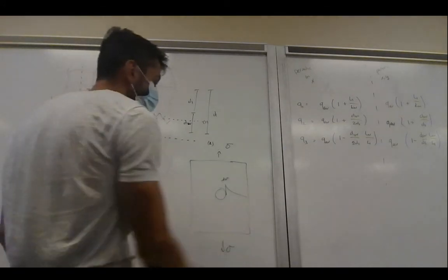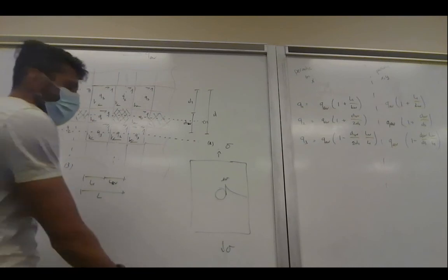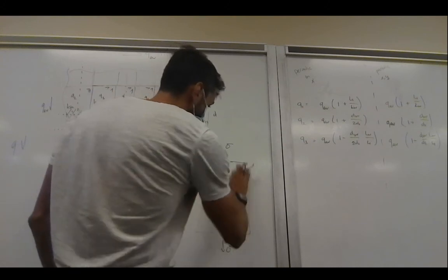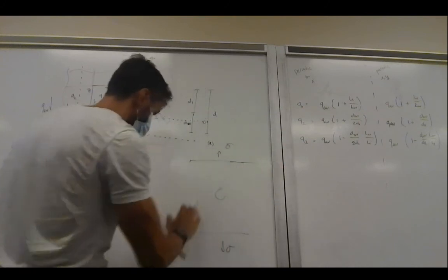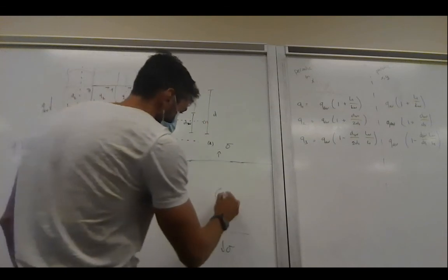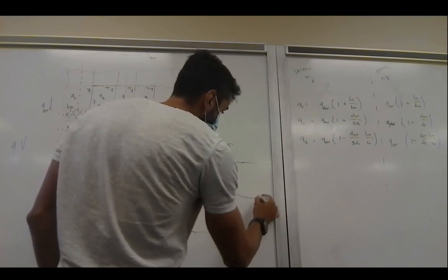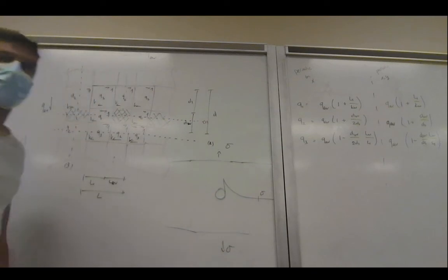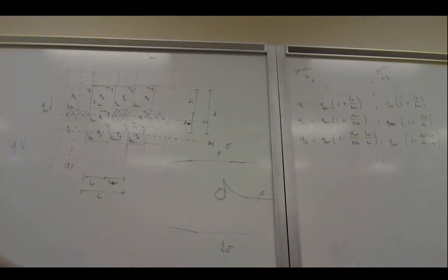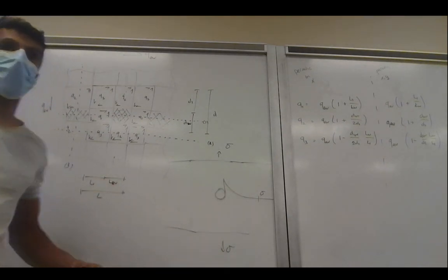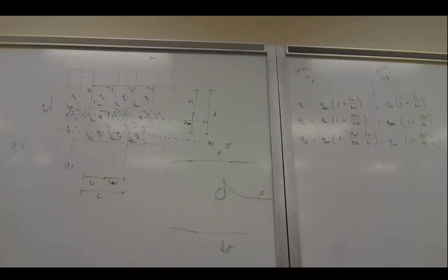And if this plate is long enough and wide enough, what you will see is that after a certain point, say this is our plate, this is our hole. So yes, we had here 3. At one point, it basically dies out, and at this location, the stresses are still our applied stress. So far away from our hole, the material does not see an effect of that hole presence. And that's what we mean with our average shear flow, far field shear flow. So far away from our cutout, we have a given average shear flow.